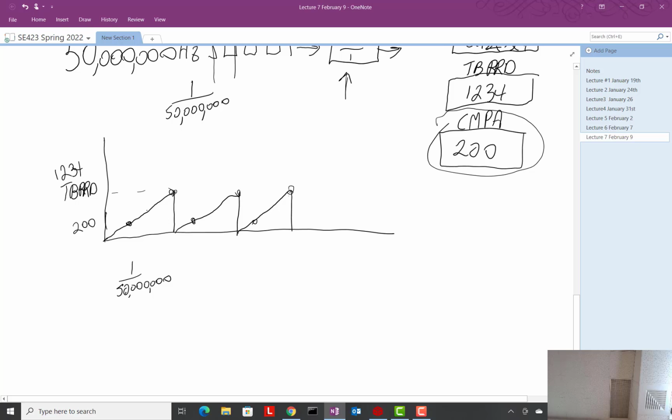Okay, let's think about what that does. Draw, erase. You have to talk every time I talk that through. It's kind of funny. All right, so let's say what we want to do is when we see this, we want to pull the IO pin low. Now, we can also, there's an event when it equals the period, and there's also an event when the counter equals 0. I don't know if that's 1/50 millionth difference from each other. I don't think there's much difference. So anyway, I usually use the 0.